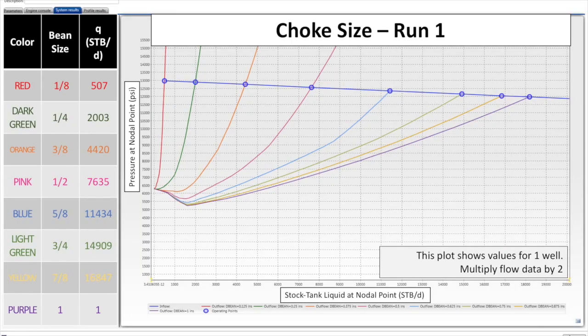In our well, we used different choke openings that were both smaller and larger than the initial opening of the base case, which used 1/4 of an inch. At first, the openings used ranged from 1/8 of an inch to 1 inch.